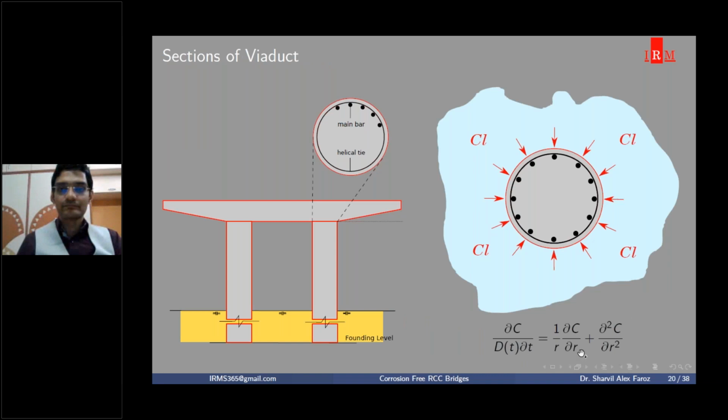So in this relationship, at the bottom, you can see this equation. This D is a function of time, right? So we consider this diffusion to be a time varying factor for our analysis. Generally, this kind of relationship is time varying up to a certain time because of these pozzolanic reactions which are taking place, and after that certain period we assume that they are constant.